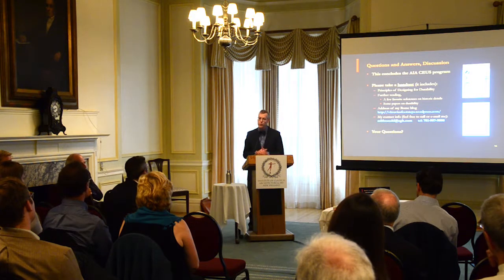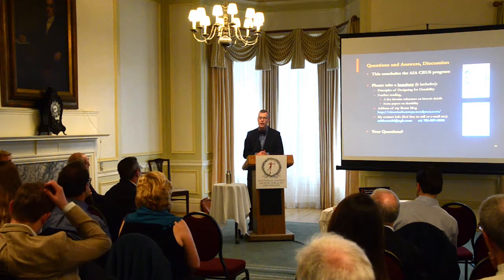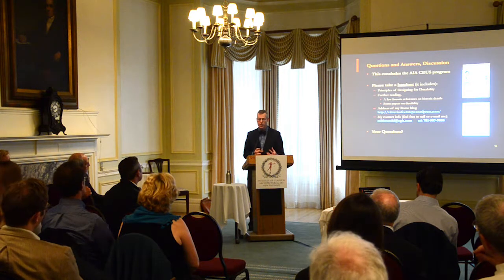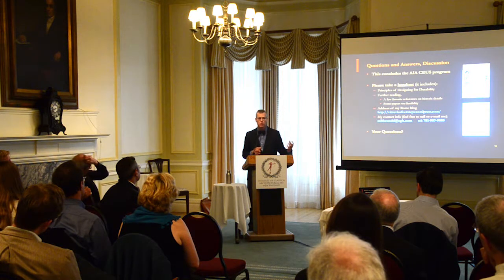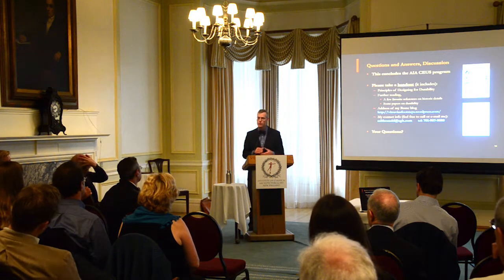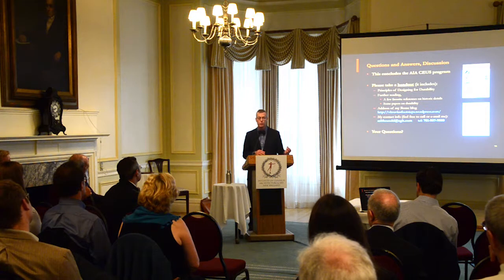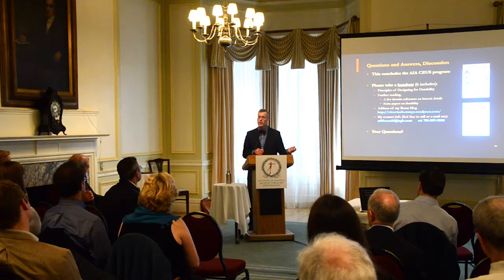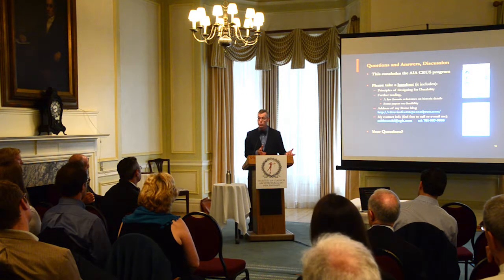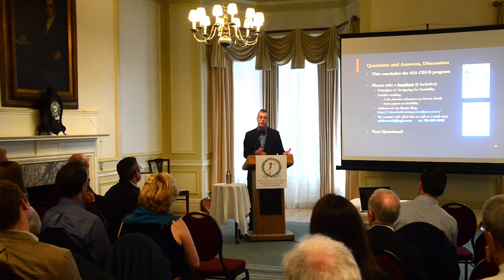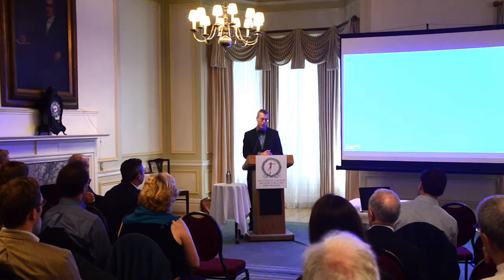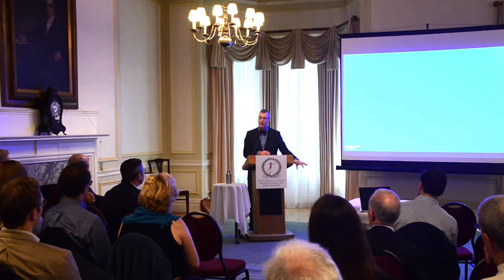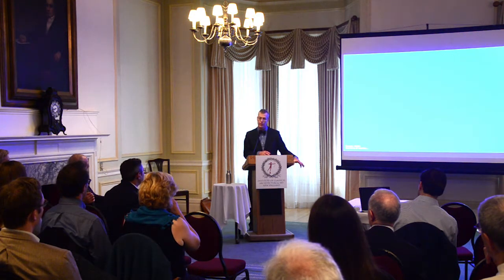Yeah, so they did use volcanic ash, pozzolana, and that's what imparts what we would call the naturally hydraulic quality. A lot of times when you go back and look at a 1600s, 1700s, or early 1800s building in the U.S., you have a pure lime mortar. And lime mortars are not very durable at all. Some of them have a naturally hydraulic property and a lot of them don't. What that means is, will it set underwater, and how fast will it gain early strength?